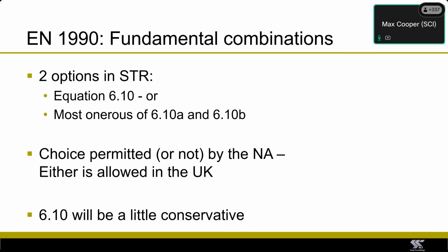One thing you may not be aware of is that the choice of using these different expressions is something that is permitted or not by the national annexes. We are fortunate in the UK that either is permitted, so that we can use 610A, 610B, but there are some other countries, for example, I believe France, that can only use 610. So we'll get on to comparisons later, but what we'll find is that 610 is a little bit more conservative, slightly easier, but in general, it's not much additional work to use 610A and 610B, and it will give you a benefit.